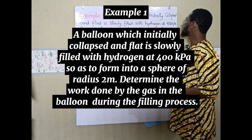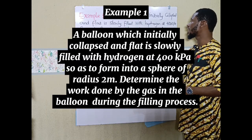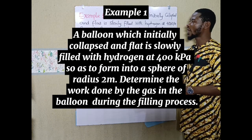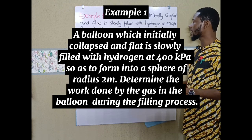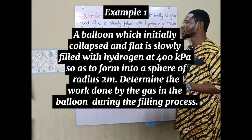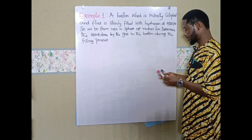A balloon which is initially collapsed and flat is slowly filled with hydrogen at 400 kilopascal so as to form into a sphere of radius 2 meter. Determine the work done by the gas in the balloon during the filling process. Solution.